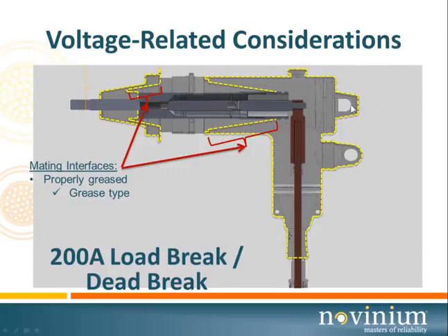What happens with the grease when it's put on in here is the pressure of the interface that's built into it pushes on the silicone grease. The silicone grease migrates out this way. It migrates out this way. There was a Yukon study done years ago where they actually found silicone grease, I believe it was 15 inches down the conductor of the cable. That's how far it migrates.